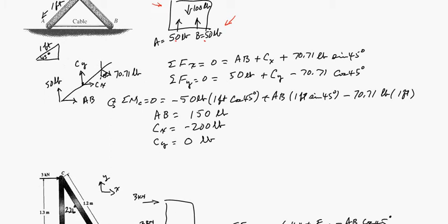And then we can draw one of these supports. And I showed you how to do that before. So we know now that this is 50 pounds. This is that cable AB. Here's that pin at C. And here is our Newton's third law reaction from the ball pushing down. And then you can sum the forces in the x, in our standard x, sum the forces in the y, and sum the moments about C.